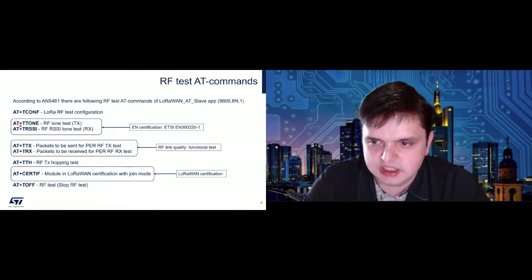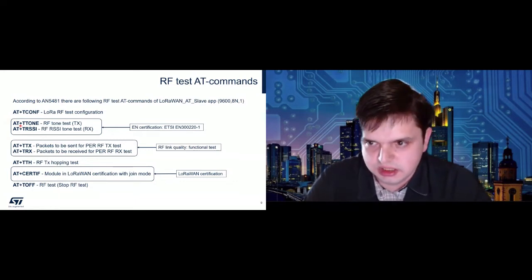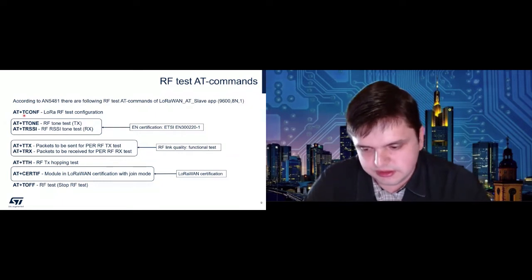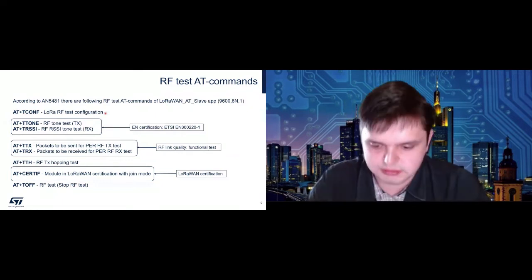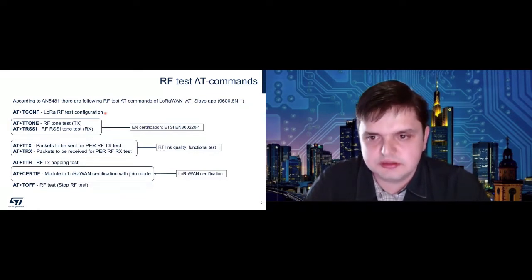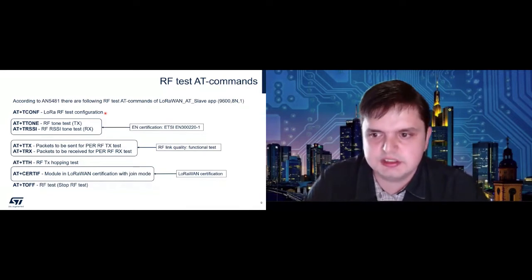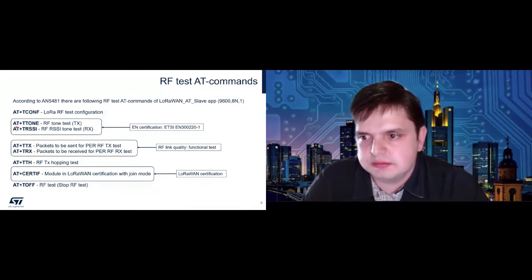So we have the AT+TTONE, or first of all, we need AT+TCONF to configure the radio the way we want it, meaning we want to transmit on a certain frequency, we want a certain spreading factor, power, etc. And then we can perform AT+TTONE or RSSI tests.